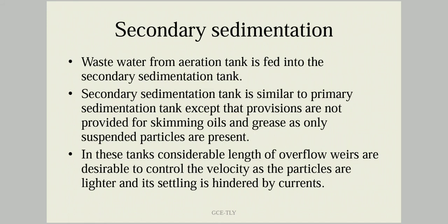After this aeration with a detention of about 8 hours, we go for secondary sedimentation. The effluent is taken into the secondary sedimentation tank, which is similar to the primary sedimentation tank, except that here we don't provide any provision for skimming because oils are already removed. Here only suspended particles are present.